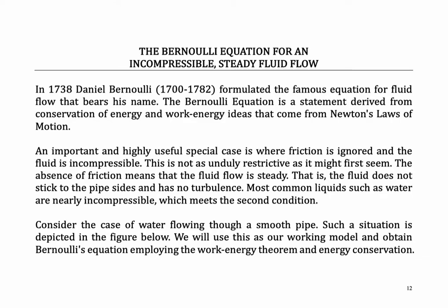of motion. An important and highly useful special case is where friction is ignored and the fluid is incompressible. So please remember the condition, which is the friction is ignored. So friction is ignored means the nature of the fluid is ideal fluid. So means there is no resistance due to the viscosity effect, and the fluid is incompressible. So means the density is not changed.